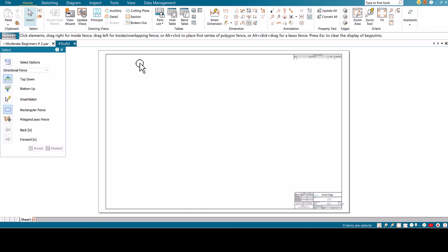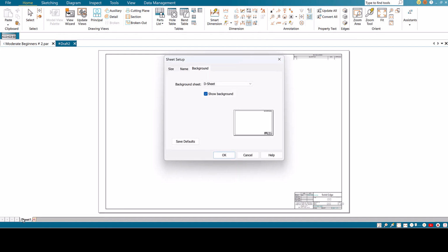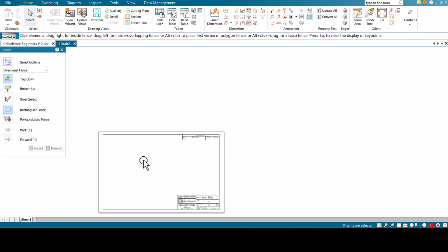Then you'll get the menu for the draft sheet. Okay, now this draft sheet is size D. This is too big, so I need to reduce it to a moderate size for our practicing or our printing out and so on. So I'm going to choose, instead of D, size B as in boy. Say okay. It comes smaller.